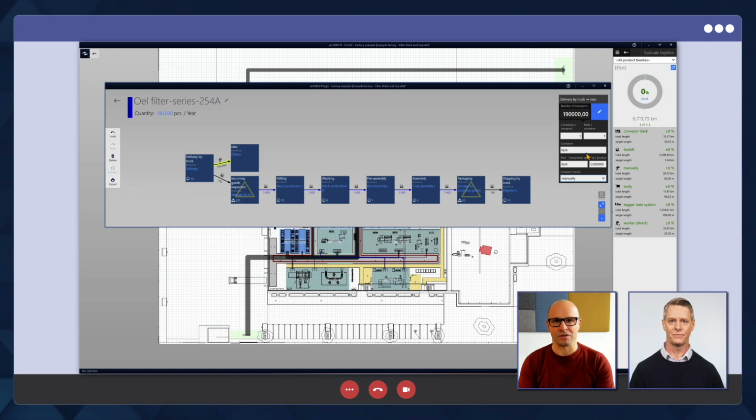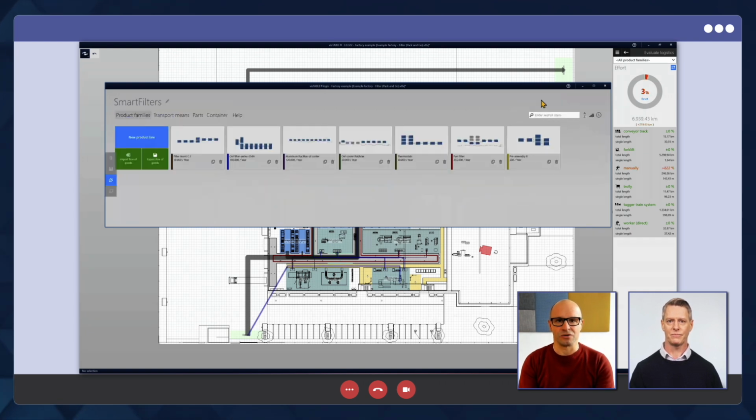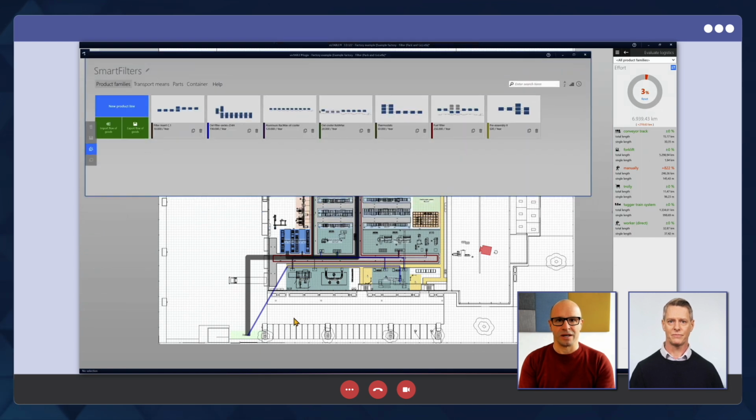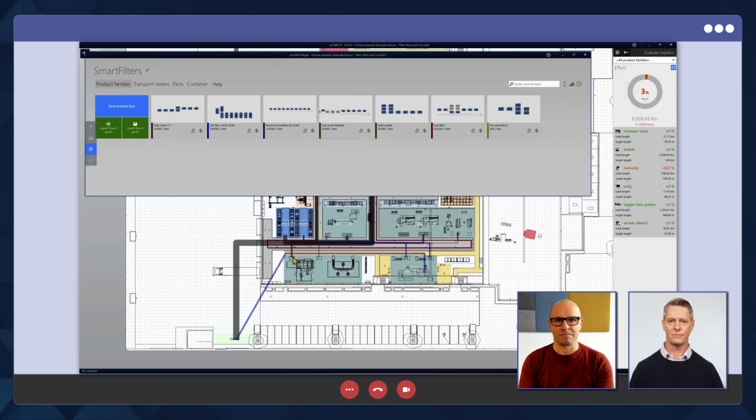If I go on here now and choose manual transport, so the worker transports one container each in his left and right hand, meaning he has two containers that he transports, and let's say there's 36 pieces in each container. Logics now shows me, based on this number, the worker would have to walk 2,639 times from the delivery to the Chiron machine. And if I now confirm this, then a new material flow arrow should be created in the layout, which we now see here. It now maps this transport, so that's how easy it is to create the material flow arrows in the layout.